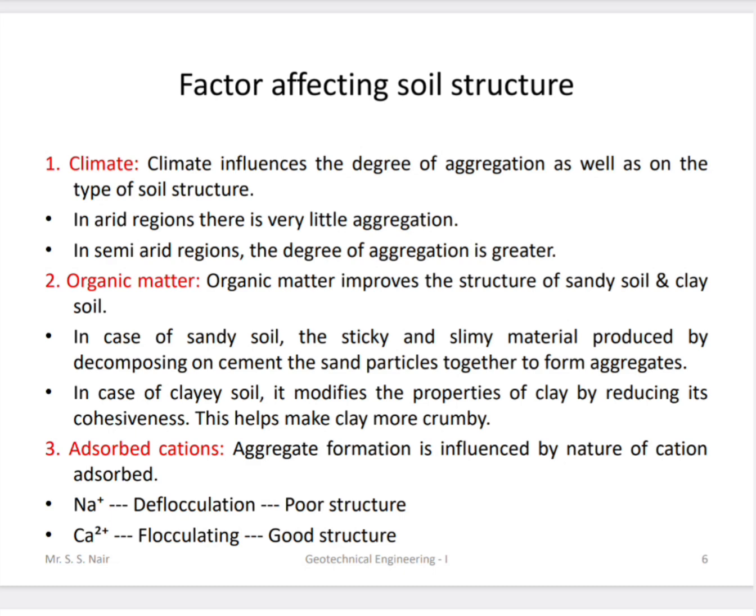Organic matter, which improves the structure of sandy soil and clay soil. In sandy soil, sticky and slimy material produced by decomposition cements the sand particles together to form aggregates. In clay soil, it modifies the properties of clay by reducing its cohesiveness, and this clay forms crumbly.